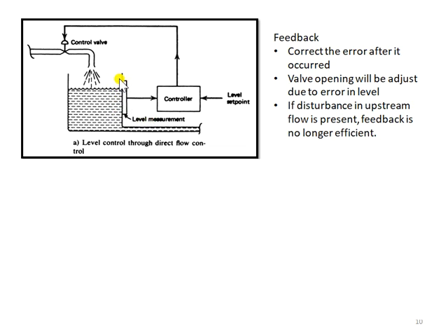So based on this observation from the sensor, the controller will determine the controller output, whether the opening of the control valve is sufficient to maintain the level, or the controller needs to change the opening, whether to increase or to decrease the opening of the valve.